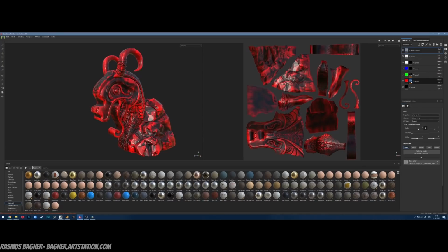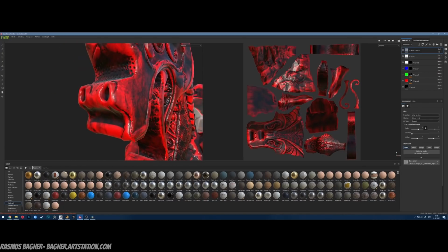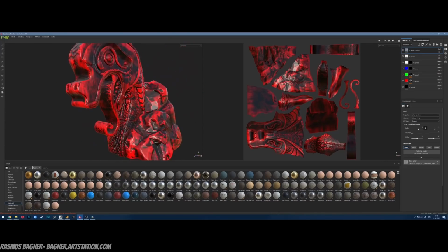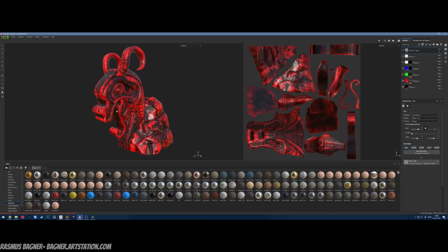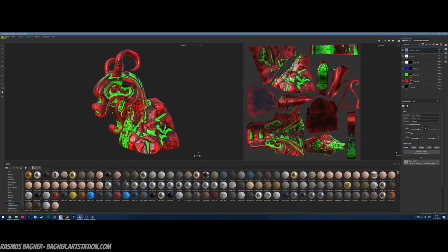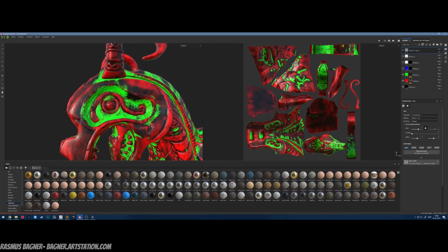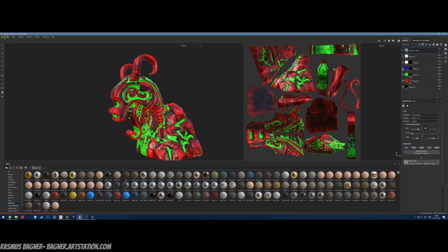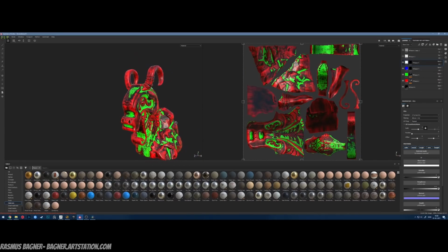Then whatever is in the red channel, in this case usually at the edges, would be lighter. So in Unreal, I simply use this mask and it automatically puts on a lighter hue where there's information in the red channel. In the green channel, I use it to darken some areas, so I put it in the cavities. I have not used the blue or white channel for anything, but you could use it for anything. The blue could be snow, the white could be dust, whichever you want.